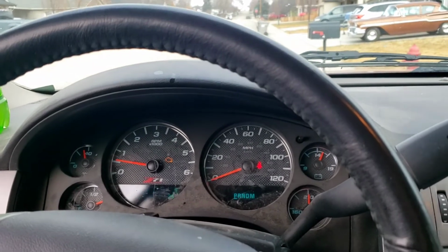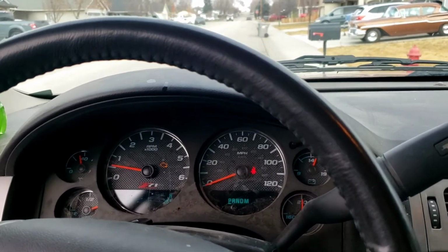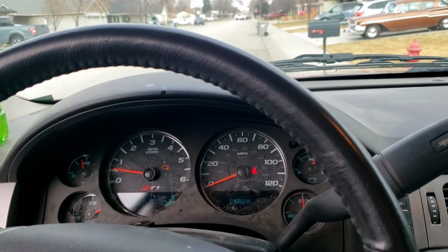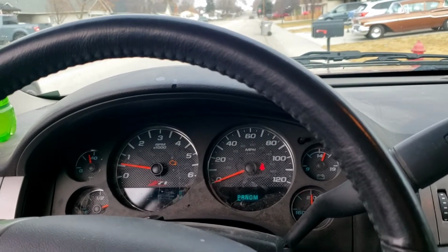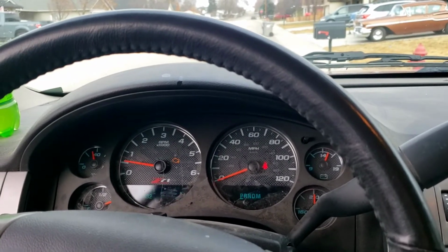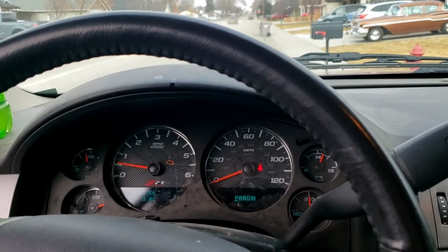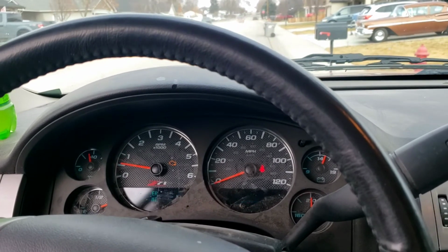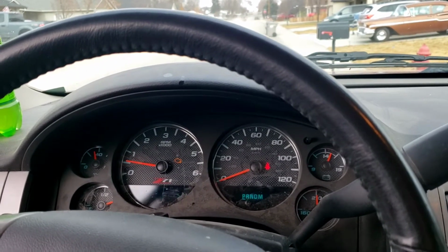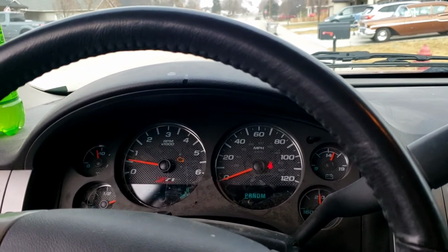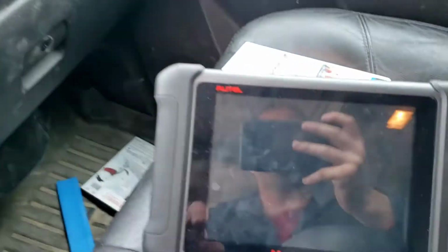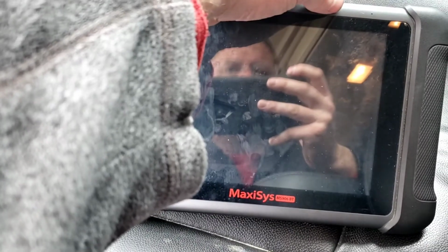So what I typically do is I look at the scan tool data for the fuel tank pressure sensor, which they call the FTP. Make sure that's good. I do a purge and seal, watch the decay rate, and also, depending on what we find, sometimes hook up a smoke machine, make sure the purge and the vent are closed, and you can smoke it and see if there's any leaks that way. So that's what we're probably going to end up doing. But in the meantime,